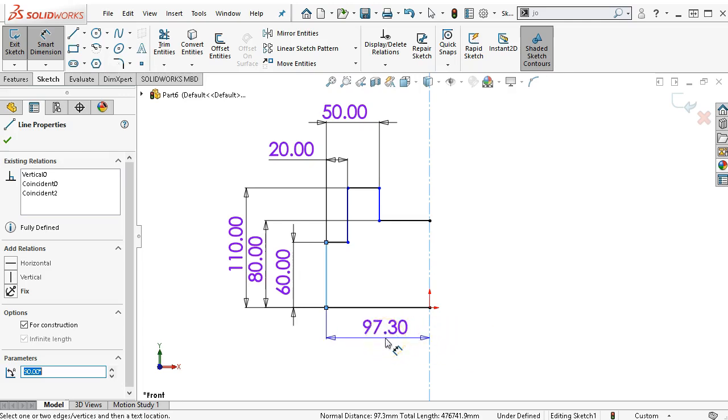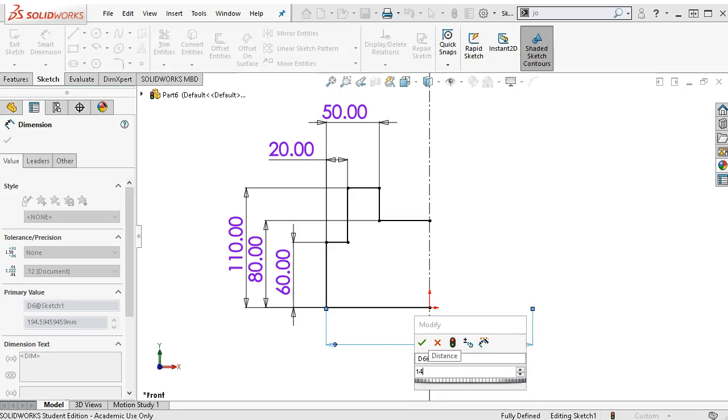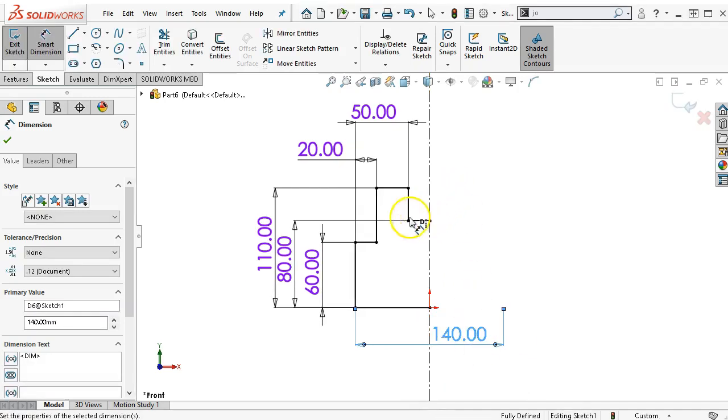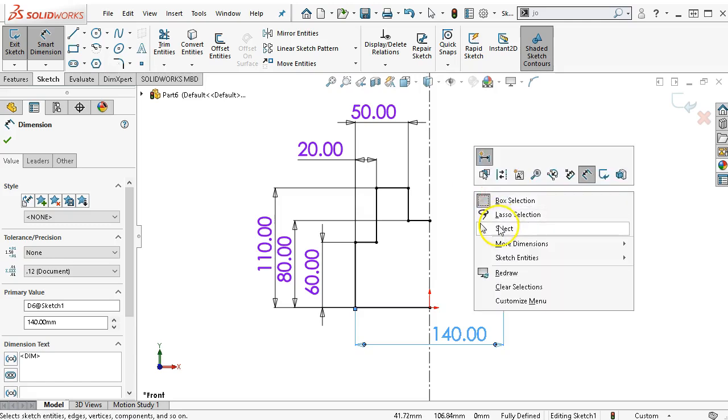So if we come back, we have radial, we go across, we have diametral, half dimension, full dimension. So my full dimension is 140, and that pulls it in, and in the process all of that stack up would give me the 40 for the size, but I do have to make sure that that is also going to end up symmetrical. So the 20 back, the 90 minus 140 would be 50 to the inside edge. We have those in place.